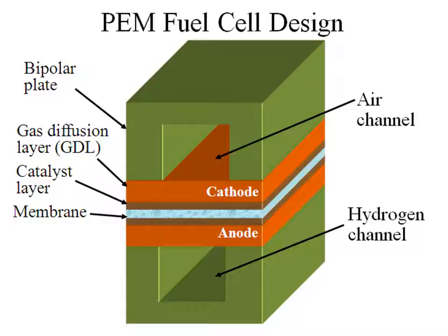And then after that, you finally get to your catalyst layer. So this would be the cathode catalyst layer in the dark brown. The light brown, reddish brown is the gas diffusion layer. Dark brown is the actual catalyst layer, and then shown here, this water visualization is actually the membrane, the polymer electrolyte membrane. And then you're going to have, once again, your anode catalyst layer, your anode gas diffusion layer, and then your hydrogen channel.